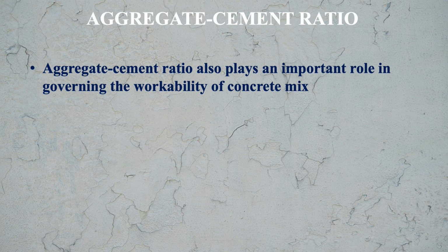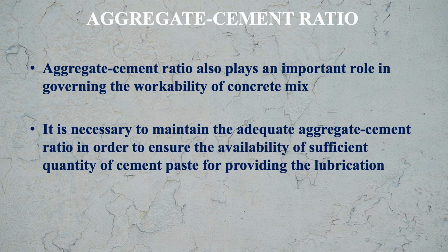Let us see the effect of aggregate cement ratio. Aggregate cement ratio also plays an important role in governing the workability of concrete mix. It is necessary to maintain the adequate aggregate cement ratio in order to ensure the availability of sufficient quantity of cement paste for providing the lubrication.